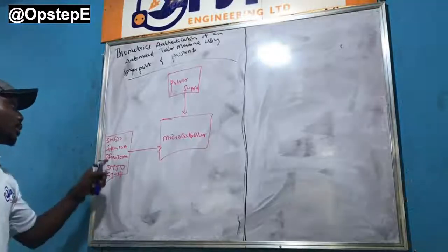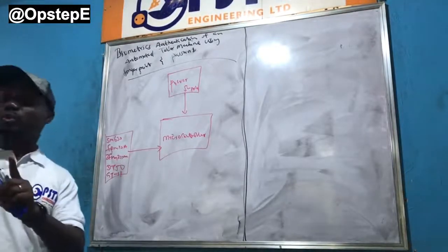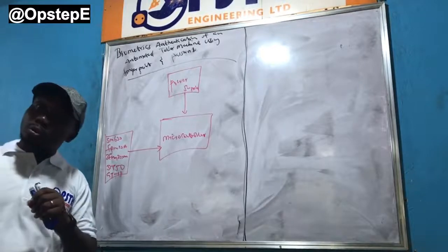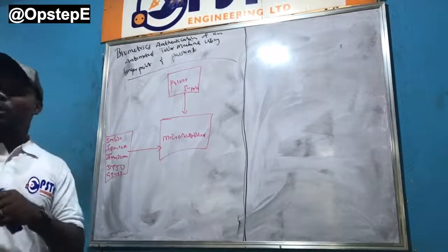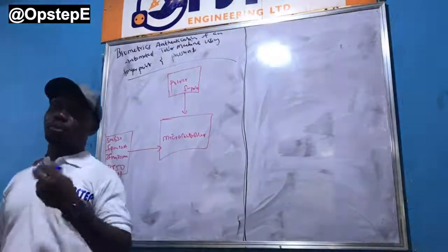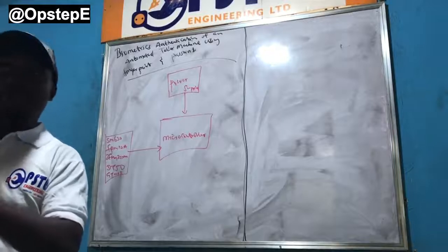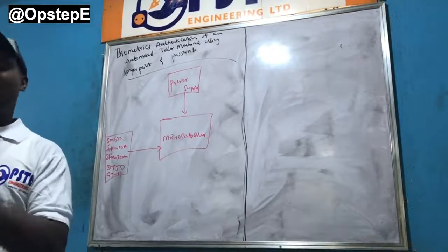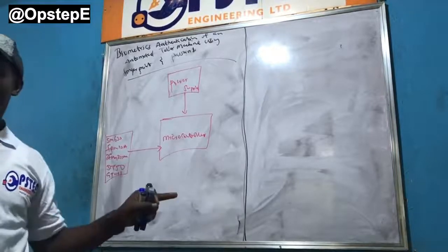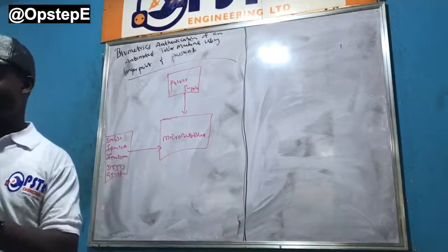Now, truth is, based on the part number, if you get the data sheet for the specific one you bought, which is something I advocate, that when you pick up a sensor or any device for that matter, it is very important that you pick up the data sheet and hear what the manufacturer has to say. It is in the manufacturer data sheet you're going to get its power requirements, whether it's operated with 3.3 volt or 5 volts.